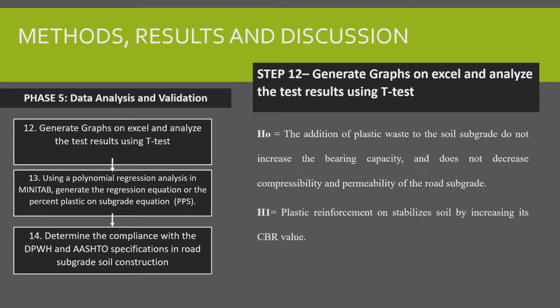The data analysis and validation phase is composed of 3 stages, having the first stage as to generate graphs on Excel and analyze the results using a t-test. So we have the null hypothesis as: the addition of plastic waste to soil subgrade does not increase the bearing capacity and does not decrease compressibility and permeability of road subgrade. And its alternative hypothesis is: plastic reinforcement stabilizes soil by increasing its CBR values.